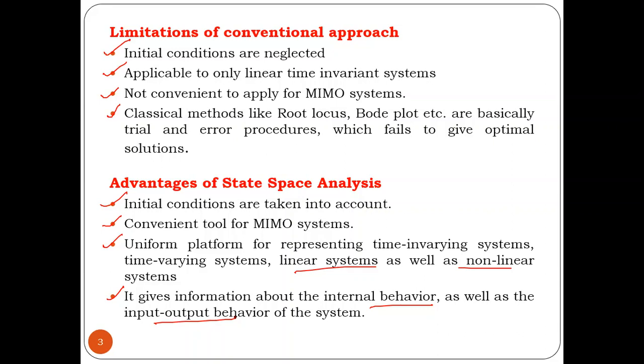That is output by input, which gives the transfer function directly. In between, at each node or at any takeoff point or summing point, what is happening? What is the state of the system? That cannot be determined. But in the state space domain, the state at any node can easily be analyzed because state space representation involves the state variables. The state variables tell what is happening in the middle, the internal behavior of the system.